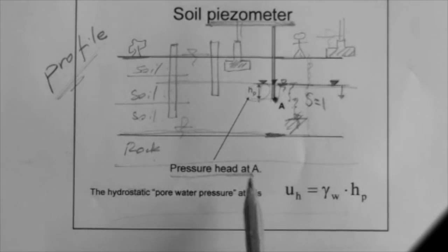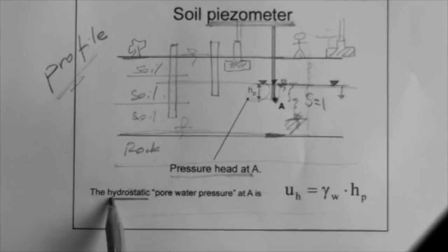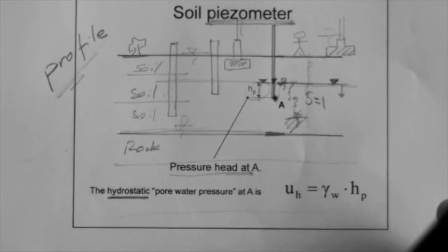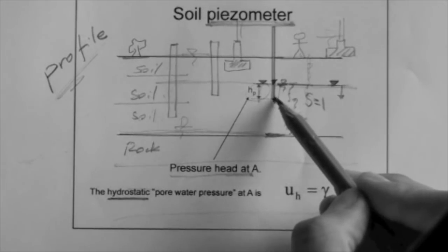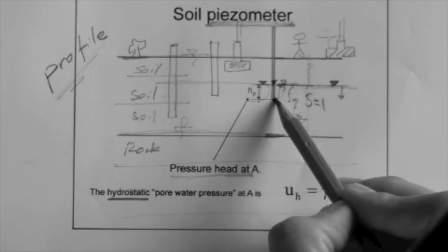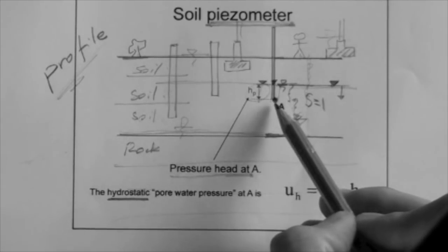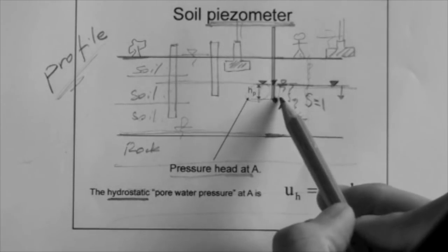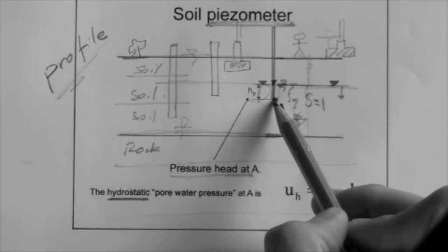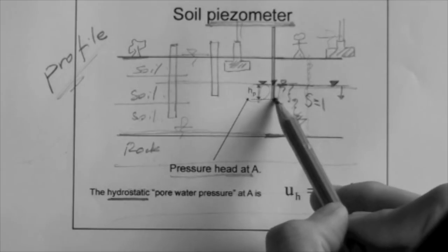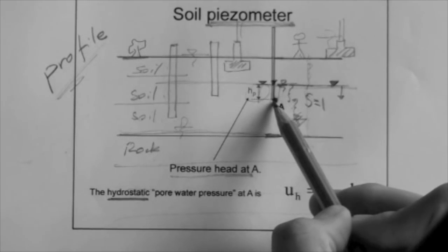And so now we can actually define what is the pressure. And this is the hydrostatic pressure. Why hydrostatic? Because the water is not moving, first of all, and the water is not suffering a pressure that is not due to its own self-weight. The reason why this point is under water pressure is because there is weight of water above it. And the only reason there is a pressure at this point is because of that.